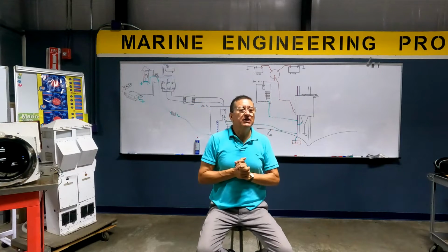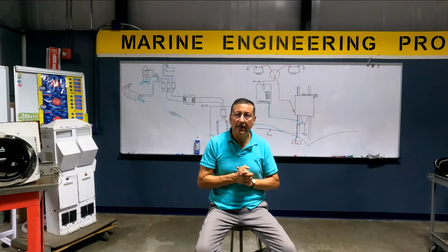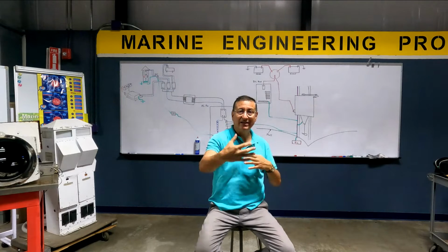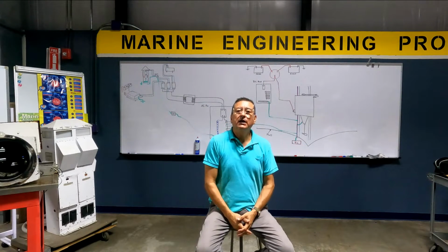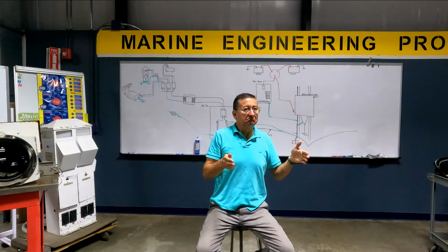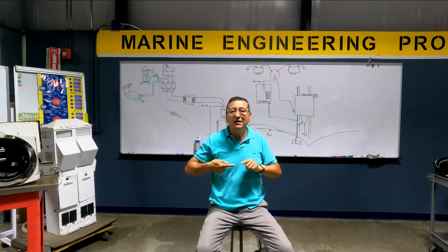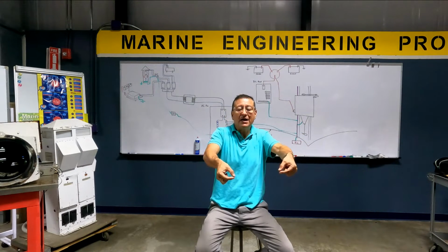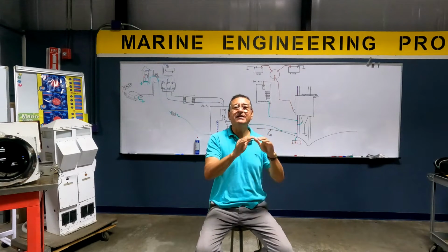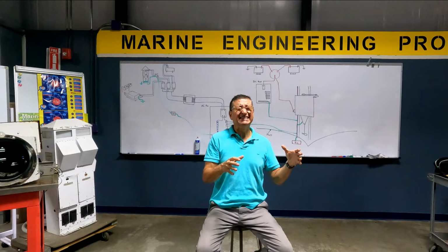Let's imagine that I have a dishwasher with no bonding in my boat. All the static electricity accumulates in the case of the dishwasher. The case is steel, not stainless steel, just plain steel. The rivets are copper, and the frame is aluminum. You have dissimilar metals together with electricity accumulated there.